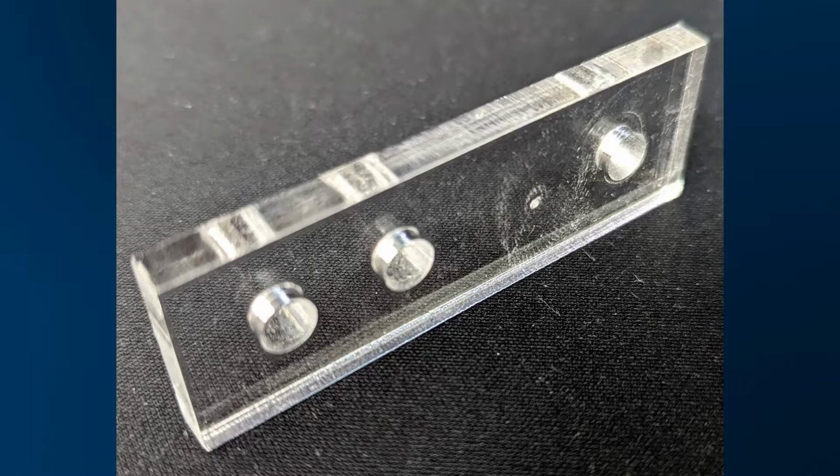Here we have another very popular use for laser cutters. This is a piece of acrylic. Acrylic is not to be confused with polycarbonate. If you go to a Home Depot or a Lowe's, they're both going to have these materials present. Acrylic can be laser cut, polycarbonate not so much. Acrylic is brittle. If you try to bend acrylic, it will break and snap. Polycarbonate will not. It will bend and yield.